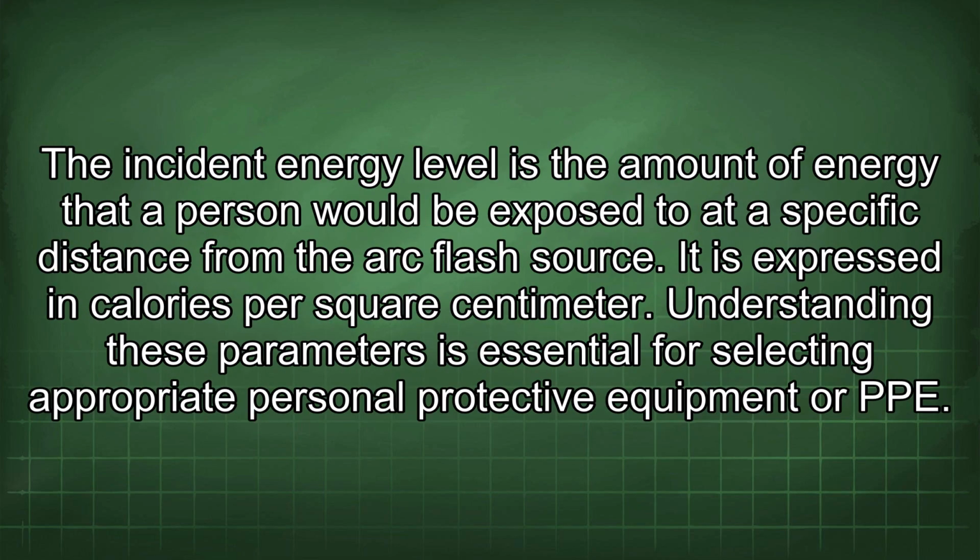The incident energy level is the amount of energy that a person would be exposed to at a specific distance from the arc flash source. It is expressed in calories per square centimeter. Understanding these parameters is essential for selecting appropriate personal protective equipment, or PPE.